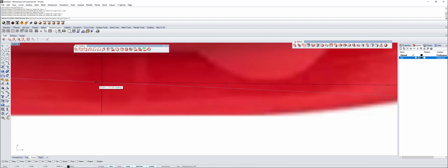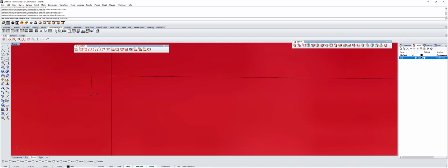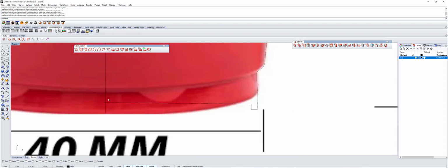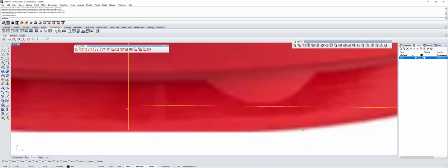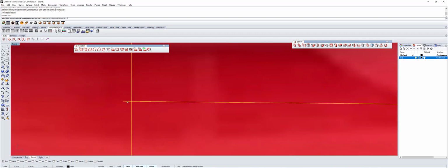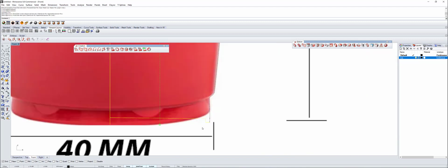And I'm going to pass the center line, and then I'm going to use the command Trim to trim this piece of line over here. So I'm going to press enter to finish. Now I'm going to select this line with the middle one, and I'm going to take Trim. What I'm going to do is trim this little piece of line over here that I don't need, because I need this to be aligned with this center line. So click it, enter.